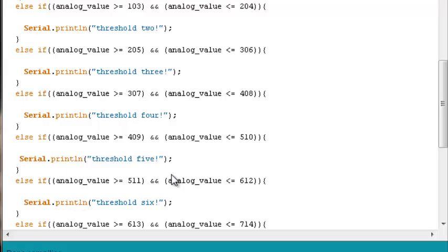It's not very pretty. It's kind of ugly. Many times doing view meters, spectrum analyzers, adjusting motor speeds, etc., based off of some incoming analog read value. And it works every time. Now, is it slower or faster than the alternative procedures? Well, it depends on what you have it doing. With old serial print stuck in here, nothing's going to be fast. I mean, serial print takes time for that serial message to get sent, received, and confirmed. But it's speedy. And if it's a visual display, oftentimes you can use this if and else if structure.